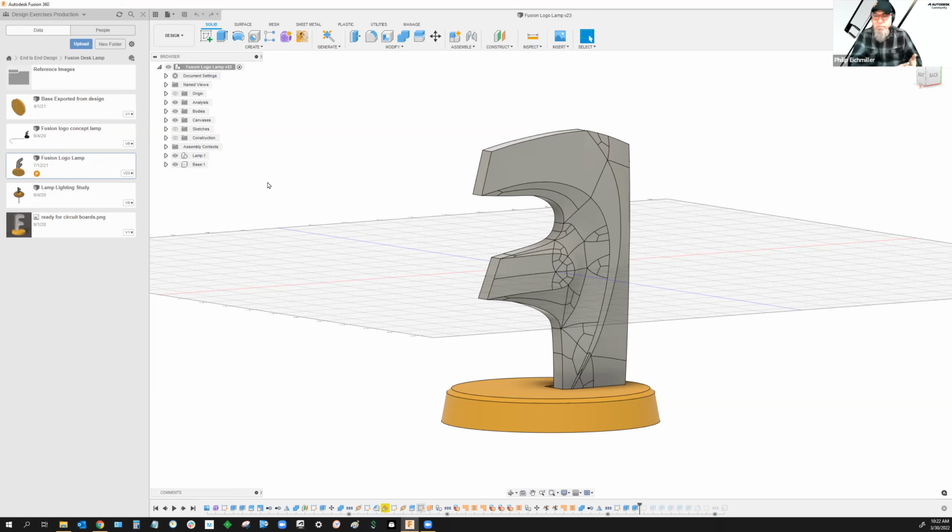I have a model for each of them. That way, all of my drawings will only show fasteners that I know my purchasing agents can purchase. A nice lean manufacturing model based on a list of standard components. That might also include connectors, electronics, audio connectors, all the things I used to design. Anything that was purchased could go in a library and be inserted into a design as an XREF, because I never really planned on changing those things.